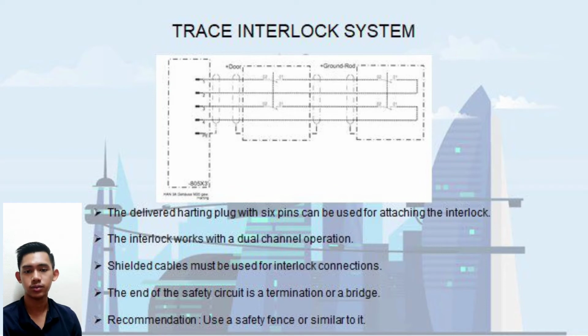For the interlock connection, shielded cable needs to be used. The cable shield must continue through the connectors. The end of the safety circuit is a termination or a bridge. I recommend you use a safety fence or similar for your own safety. That's all for me. Thank you.